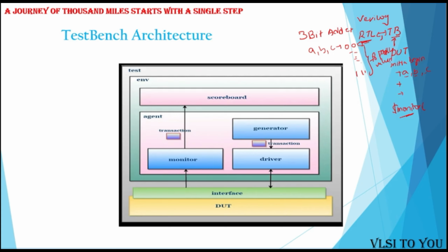But as I already told you, when you are designing complex circuits, this is not as easy as you think. So, in order to verify any kind of circuit by reusing techniques and using many advanced features in SystemVerilog, this architecture is built. Now let us see what is happening in SystemVerilog. We are taking the same example of the 3-bit adder, and we are going to write the testbench architecture for SystemVerilog.